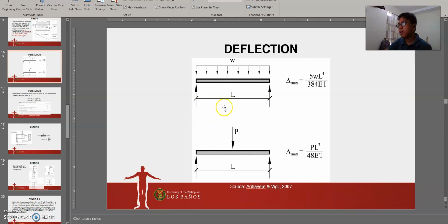Since this is live load, that would pertain to the concentrated moving load, where should we put the live load for maximum deflection? There's only two answers, of course, in all these questions. It may be in the midspan or in the support, because that's where the maximum values occur. And in the case of deflection, as you can imagine, it should be in the midspan, right?